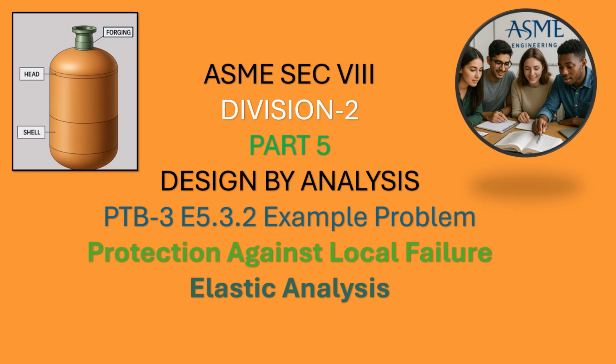We will again use PTB-3 examples, specifically example 5.3.2 and 5.3.3, to see how ASME requires us to evaluate local failure using both elastic analysis and elastic plastic analysis. Just as before, I'm referencing the 2025 edition of ASME Section VIII Div 2, so section or clause numbers may be slightly different from older versions. Also, there may be small differences in the results because PTB-3 doesn't provide CAD geometry. We must recreate the model from the given dimensions, which can lead to slight variation.